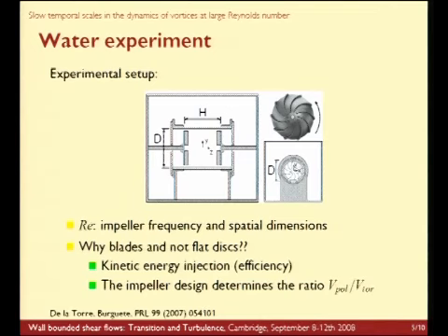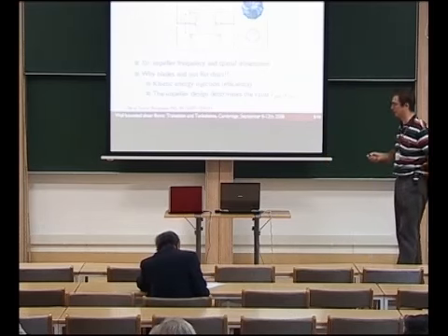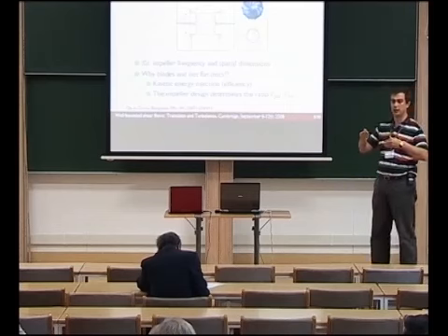You may ask why the impellers have blades and are not flat disks. This is a question that the people who work with numerics ask a lot. But there are two reasons. The first reason is that we wanted to inject as much kinetic energy in the volume as possible, and the blades are much more efficient than flat disks. But the second one is much more interesting.